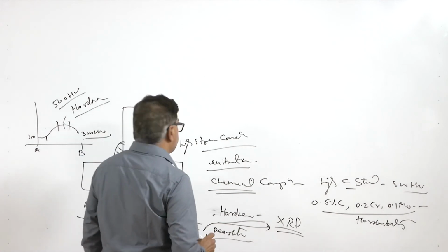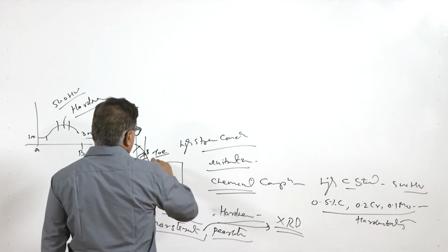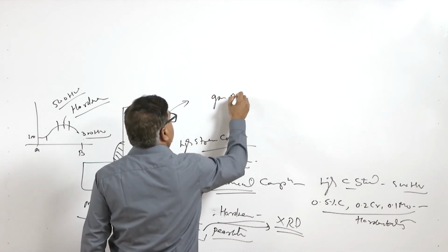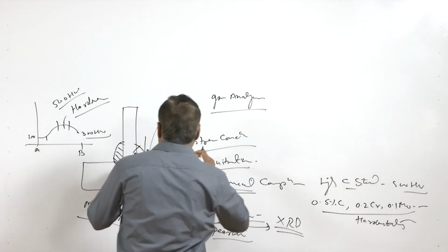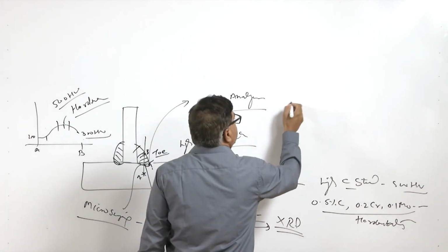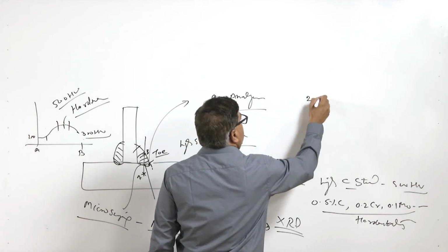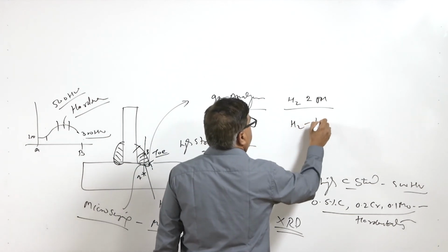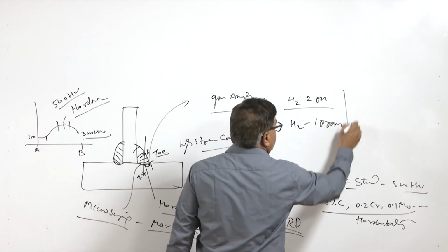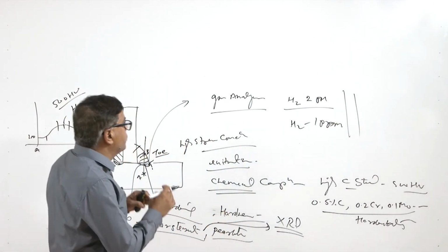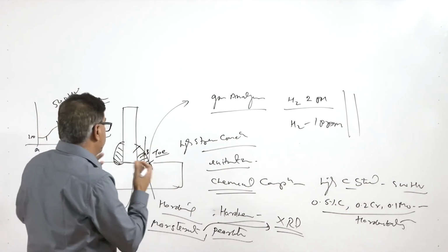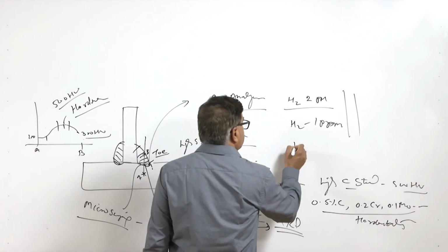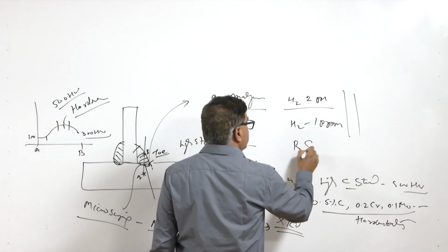In addition to this, at this location we can further carry out gaseous analysis of the weld joint as well as the base metal. The gaseous analysis may indicate that hydrogen is just 2 ppm in the weld and 1 ppm in the base metal. So, hydrogen may not be contributing significantly, and may not be a big factor towards the nucleation and growth of the crack. But certainly we can also do the residual stress analysis.